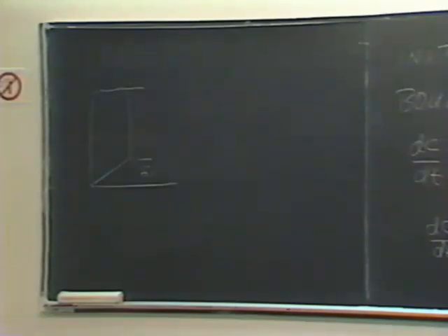Yeah. How to decide erosion rate? I think that's the most difficult part. Erosion rate, just like erosion rate. Oh, this one? Yeah, M. M, this is for surface erosion. I described the layer by layer for bulk erosion. For surface erosion, the only way you can get that is by laboratory measurement. And so, from a rotating cylinder or from